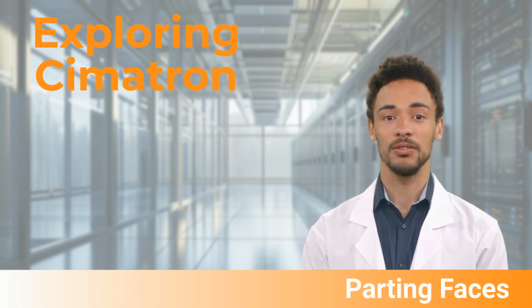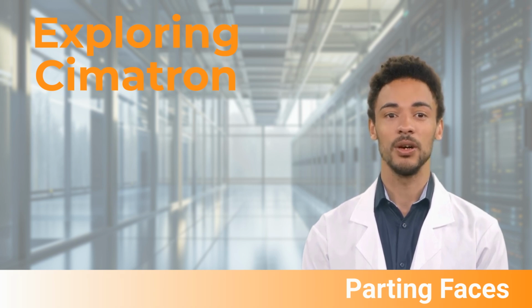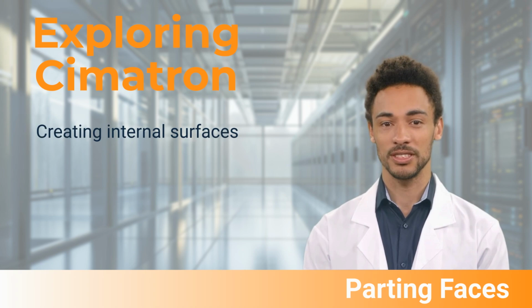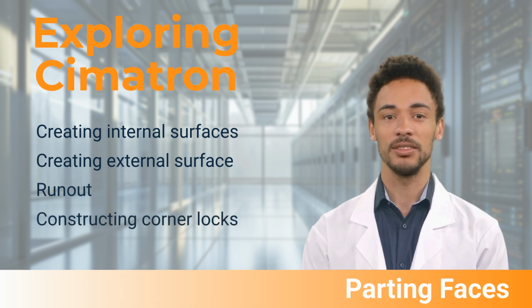In this video we will focus on the parting surface part feature of Cimatron mold design. This works hand in hand with the quick split function to establish the necessary parting surfaces to create our mold core and cavity parting surfaces. In this video we will cover creating internal surfaces, creating external surfaces, runout, and constructing corner locks.